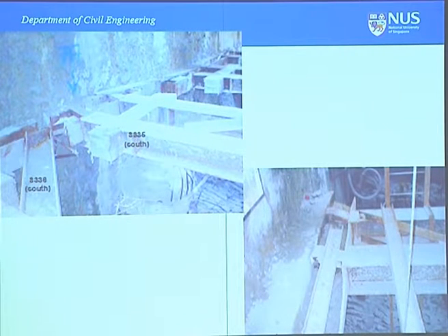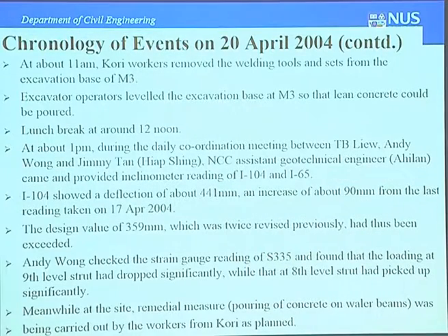Okay? So anyway, these are some of the photographs of the buckled joints. And then at about 11 a.m., quarry worker removed the welding tools and sets from the excavator. I think preparing to pull out. It's getting a bit too dangerous. So excavation operators level the excavation base so that lean concrete can be poured. What are you talking about pouring lean concrete? I mean, 28 days to gain the strength, and now the struts are buckling and you're pouring. Lunch break at 12 noon.